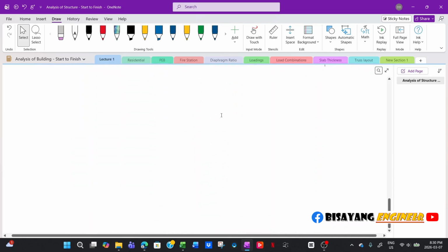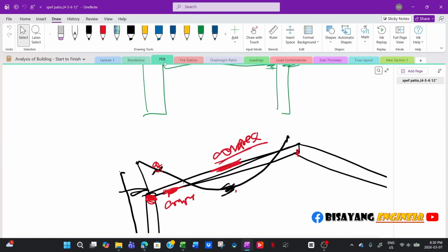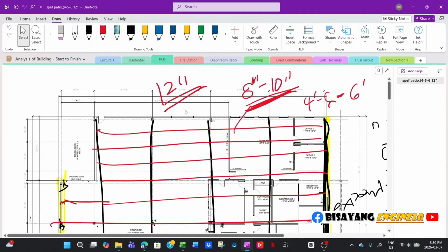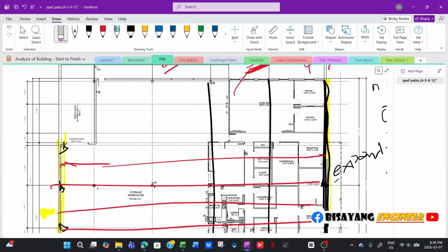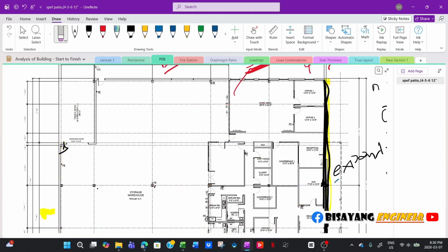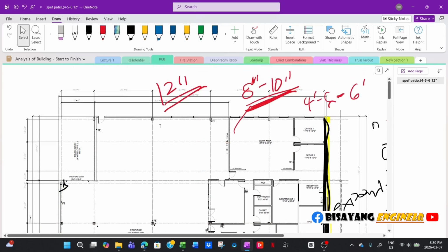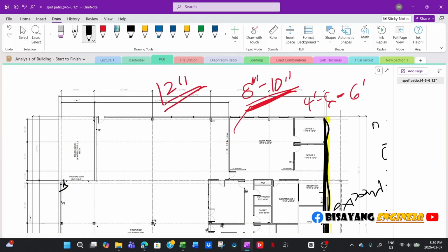Now in the roof framing plan, in our example, it really depends on how the architect would lay out the roof drain so that you will have the least amount of insulation to bring the slope, because sometimes the roof trusses are just flat, and then it is the insulation that will do the slope.